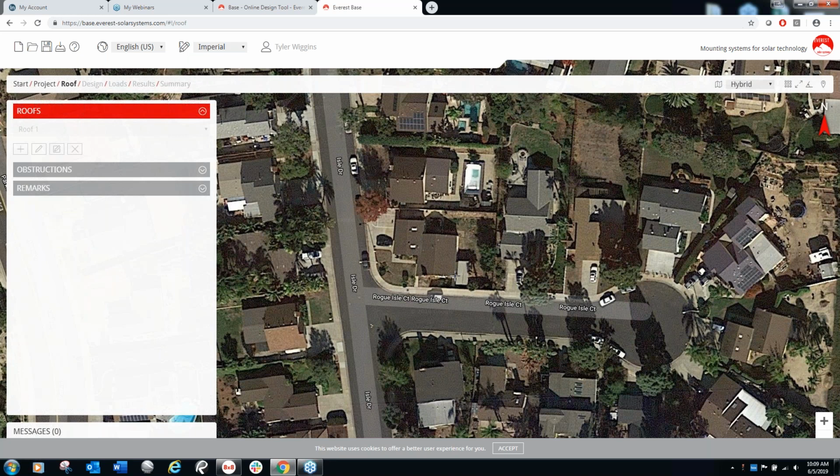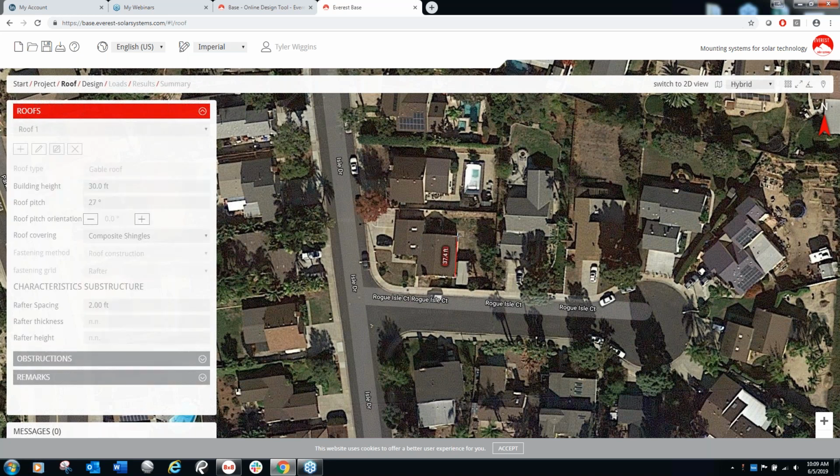So I'm going to go ahead and click in the corner, draw this up to the top, and then move this out. You'll notice that it's green. Basically, what that's telling me is that if I were to click anywhere when it's green, it's just going to lock that roof into place. So at this point, I'm going to bring it up to the ridge here on the top of the roof. Go ahead and click, and now I have my roof drawn.